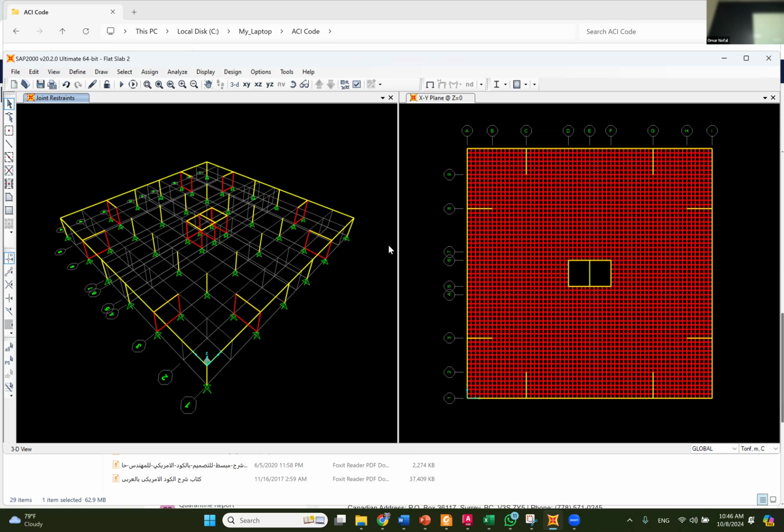Once you do the seismic analysis and wind analysis, you will get bending moment in the X, bending moment in the Y, and design it as a biaxial member. So then you will find out that this shear wall is gonna have lots of reinforcement here, lots of reinforcement at the end, at the start, and maybe also some reinforcement distributed. Depends, because the shear wall is getting the reactions like this. So it has tension here, compression here. So you have lots of reinforcement here and lots of reinforcement here. And the reinforcement gets less as you get to the neutral axis. So it depends on the moment. So basically it's the moment in this direction. But we are not designing, we just do the analysis and get the forces.